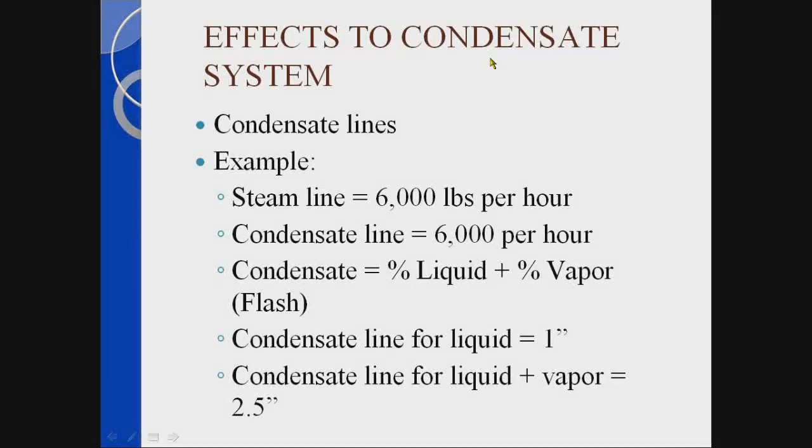I understand what you're saying, and a couple points I'll make. Your benchmark today is 90% condensate return, 90%. If you do not steam inject for process applications, you have to bring 90% of the condensate back. That's your benchmark. That's what you're trying to get to.